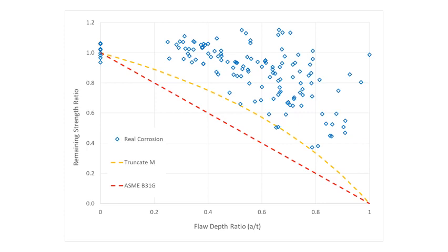We don't necessarily always think of cracks and corrosion going together. With corrosion, we're typically looking at flow strength failures, which implies plasticity. And in cracking, we tend to worry more about toughness. But one of the things we have to remember is that fatigue is a phenomenon that involves crack tip plasticity. So there is actually a close relationship there if we're looking at things mechanistically.